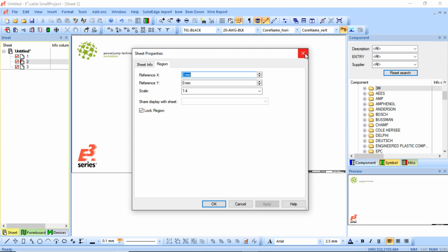So once you draw a harness drawing, you can draw it to scale. Once you print it out, you can actually manufacture to that particular drawing, which makes life a bit easier. But just for this example, I'm just going to scale it, say 1-to-2 for now, and then I'll create some dimensions as well.